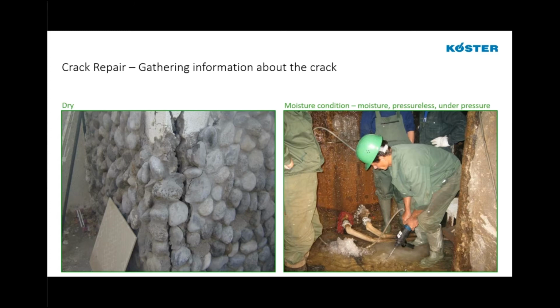But we determine what the moisture condition is, whether there's moisture present, and whether that's a pressureless injection that maybe trickles and leaks occasionally, or a crack that's under pressure that requires immediate repair because it does leak very, very heavily, as we can see in this picture here.